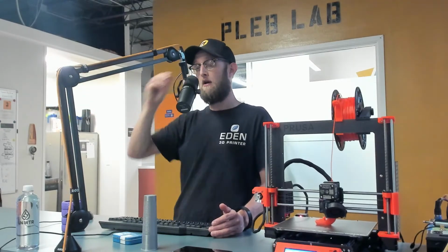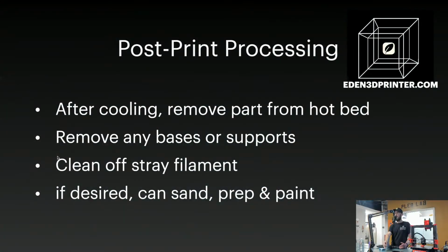Not rarely, but on occasion you will make a slight error that I highlighted earlier, where either the CAD model or the slice itself could have been slightly off, incorrect for what you were choosing to do, and that would give an incorrect print. So if you know your machine is calibrated, and you can guarantee that with a test print, something shorter than a Benchy, a 3x3 square, or whatever else, that really helps to say, okay, I know this machine is good. What's my slicing software? What are my CAD model issues?